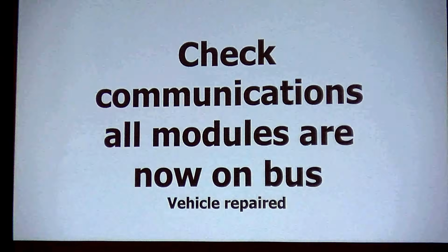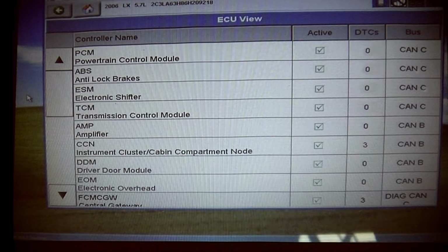Car's fixed. So we check the communications on the bus. Do you see all the CAN Cs are cleared now? They're all working? It's just as simple as a power, just a blown fuse. Don't overcomplicate this, guys. You just don't need to.